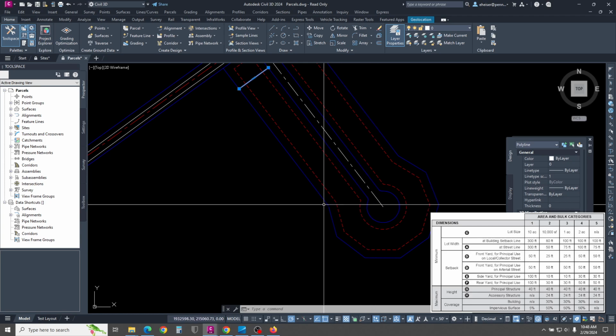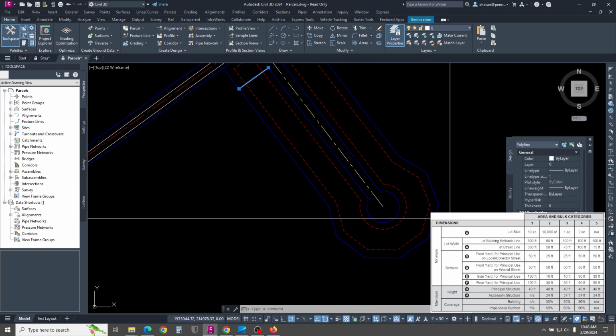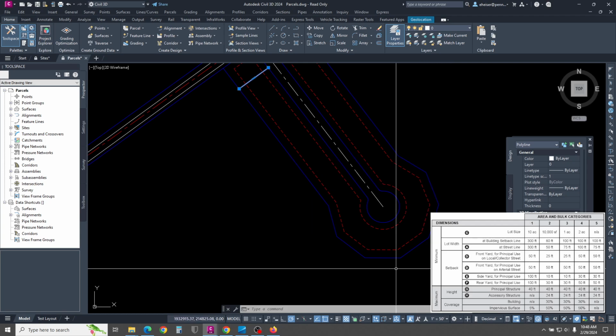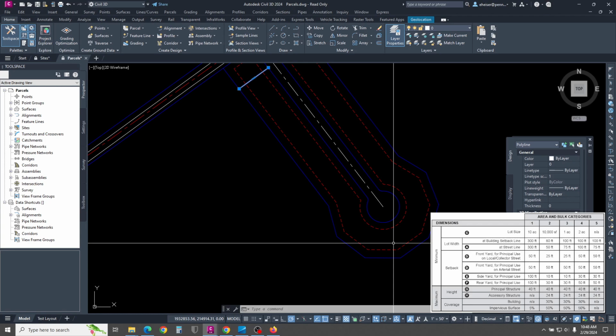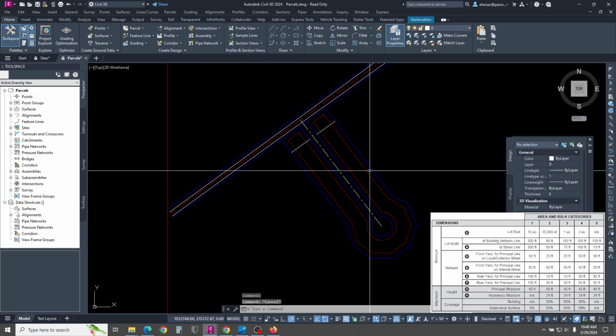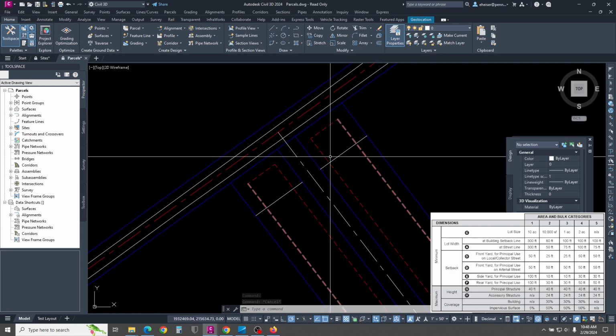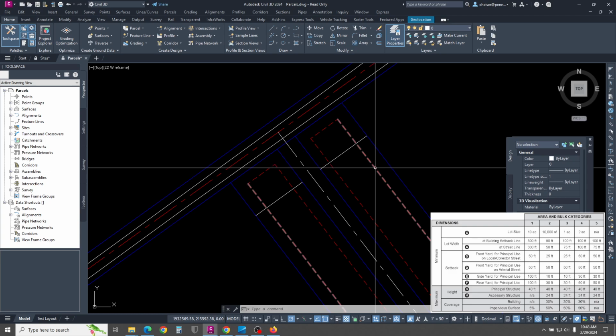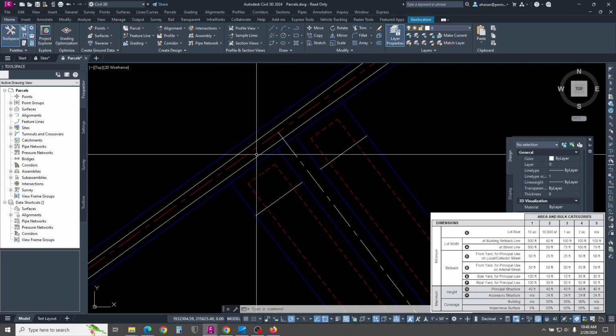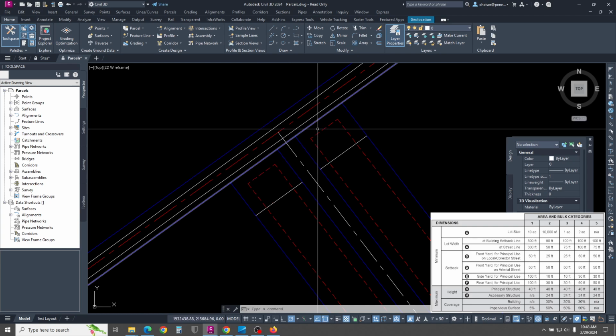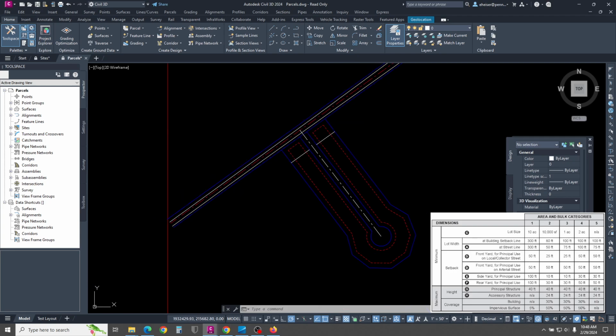It's a little bit unrealistic. We probably wouldn't have all of these short segments. There'd maybe be 3 or 4 segments. They'd be a little bit longer, but for the sake of the exercise, this is what we're going to go with. I also put some of my setbacks in. So we have 25-foot front, 30-foot rear, and these corner lots need to have a front on 2 sides, so I put 25s here off of the existing street.